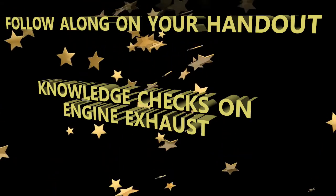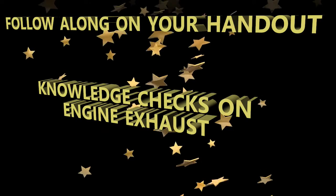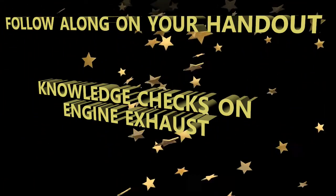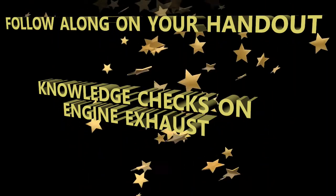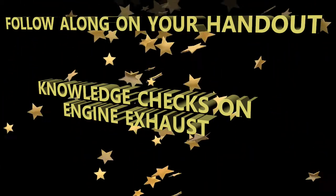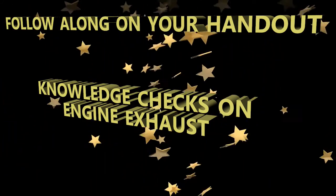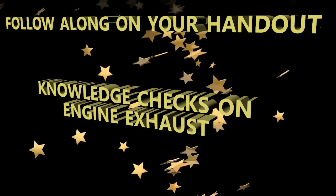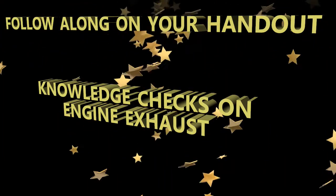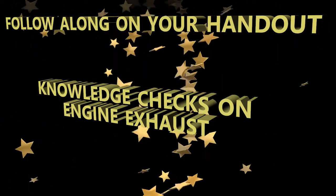All right, what component is fitted with a thrust reverser deactivation lever? Which one is it, A or B? It's the first one. Remember I said that on the hydraulic control unit there's a lever. What you want to do is put it into the inhibit position. But you don't want to just do that. The second step is getting that pin and installing it on that lever so that you can secure and keep it in that lock position.